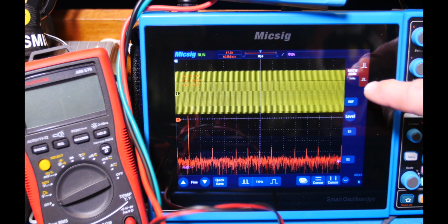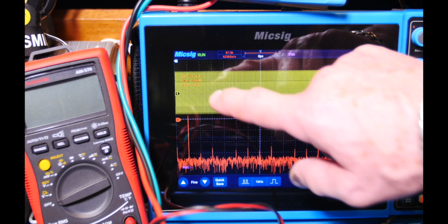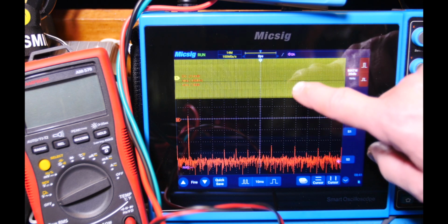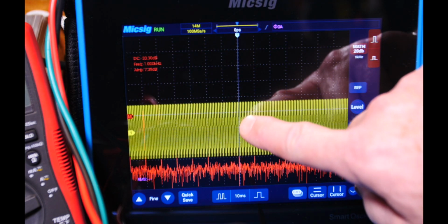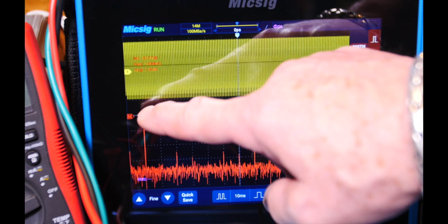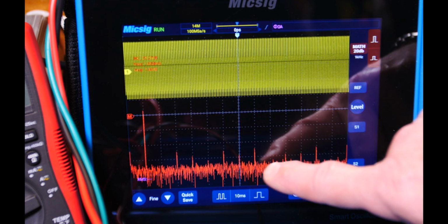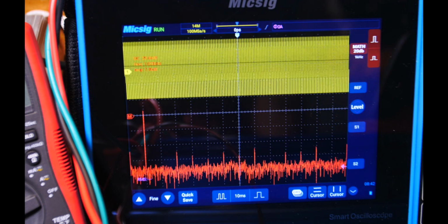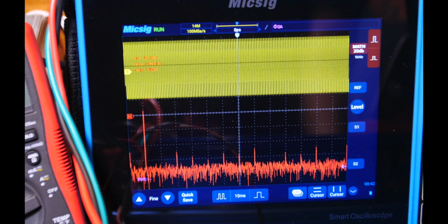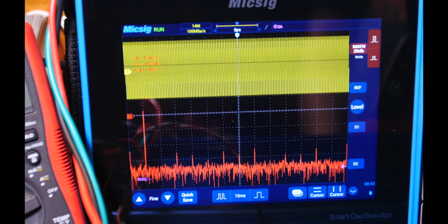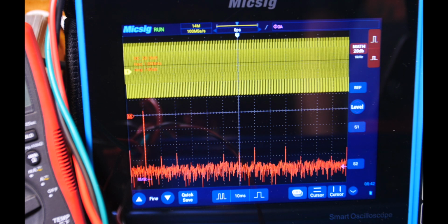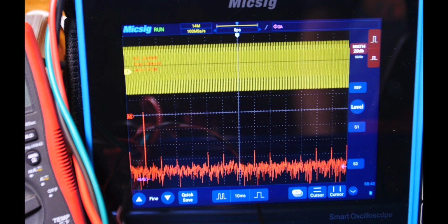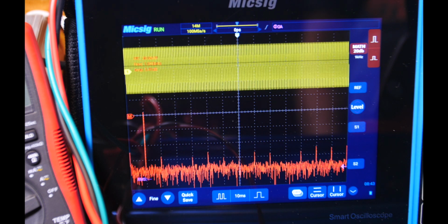Yeah, it's 20 dBs per decade. And this signal up here said 7.4 dBs. So we're about 7.4 dBs above that signal right there at 1 kilohertz. And you can see these spikes, they're 20, 40, about 50 dB below. And that's at 3 volts RMS out on my generator. So I'm going to drop it down. 2.9. That's about 2.5. That's as high as we'll probably ever use for this audio stuff.